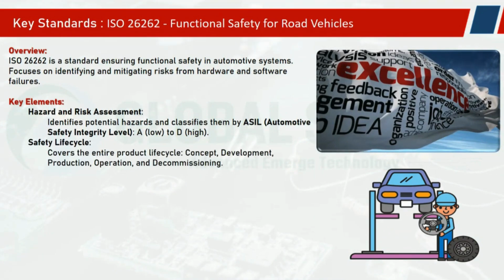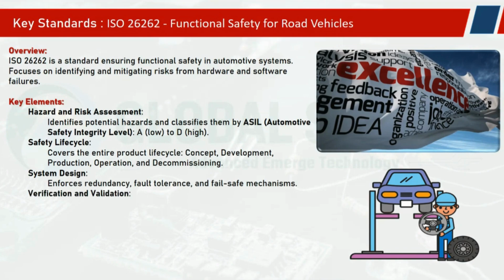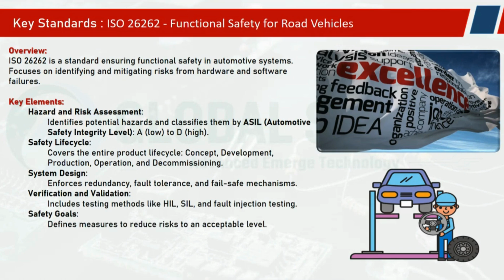Safety life cycle. It covers the entire product life cycle: concept, development, production, operation, and decommissioning. System design. It enforces redundancy, fault tolerance, and fail-safe mechanisms. Verification and validation. It includes testing methods like HIL testing, SIL testing, and fault injection testing. Safety goal. It defines the measures to reduce the risk to an acceptable level.